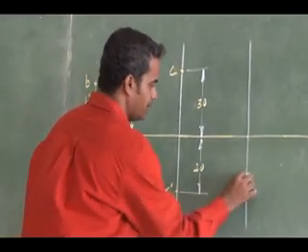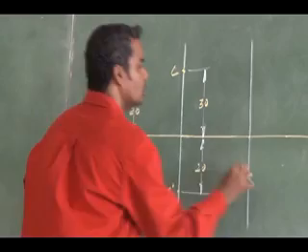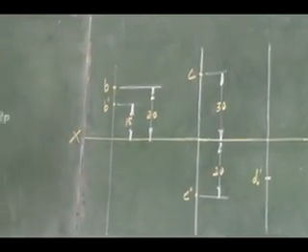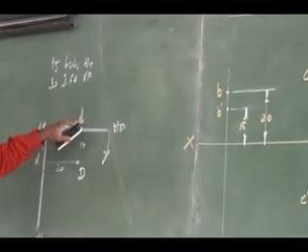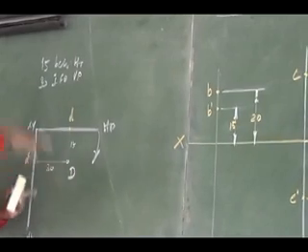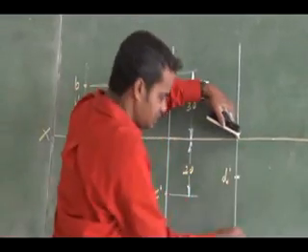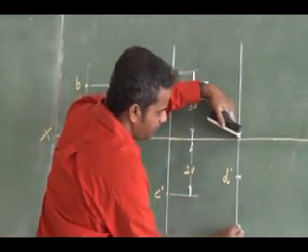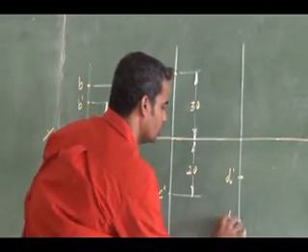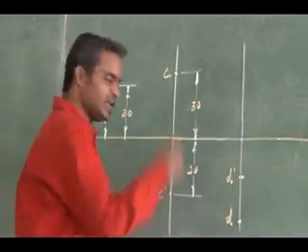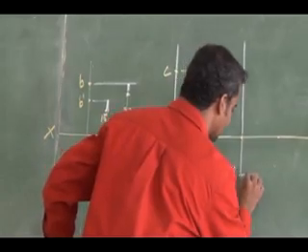It is 15 mm. So from the reference line, d will be 30 mm, and it is going to be below the reference line. So from the reference line, d is 30 mm, again below the reference line. So I can dimension this.